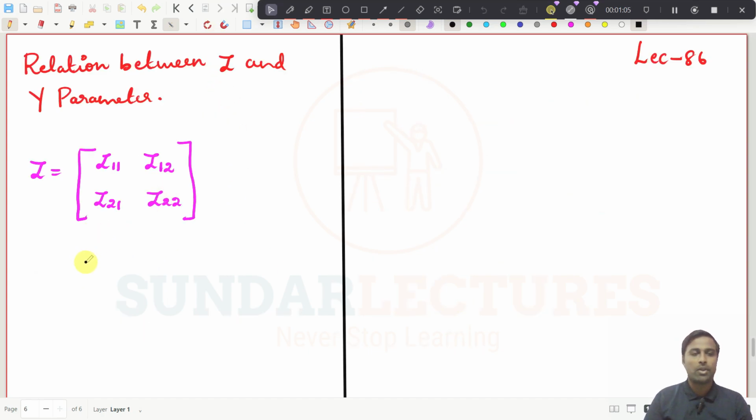So for example, let us consider this is the Z parameter, maybe Z matrix. Then if you want to find what is Y, how will you take the inverse of a 2 cross 2 matrix? What is the procedure? Y will be 1 divided by Z11 into Z22 minus Z21 into Z12, right?